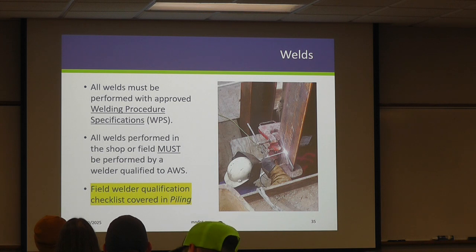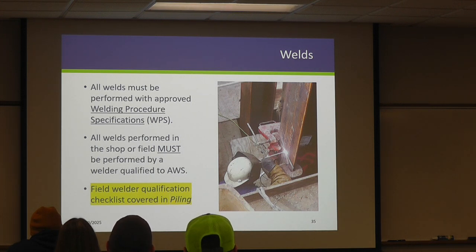And then welds. Minnesota is generally a no field weld state, with a couple of exceptions. Piling and expansion joints are the 2 main ones where we permit field welding. Very, very rarely are you going to see any sort of field welding on a structural beam, but if you do, it needs to be accompanied by a weld procedure specification, a WPS. It has to be performed by an AWS certified welder that's kept up on their continuity records. We talk a lot about field welding in the piling section. We've developed a really nice checklist for folks too, to make sure that the qualifications being presented to you are accurate and meeting the needs of the project.